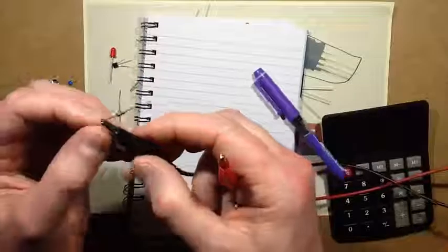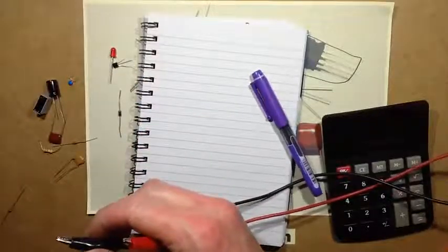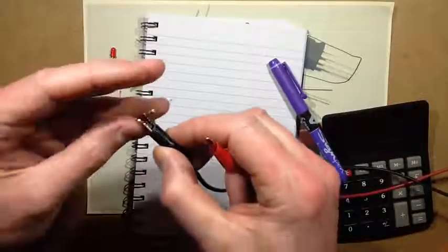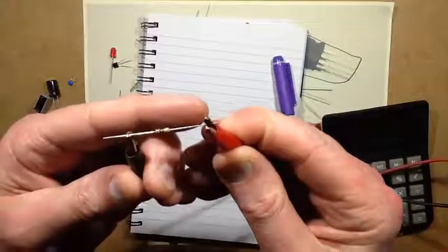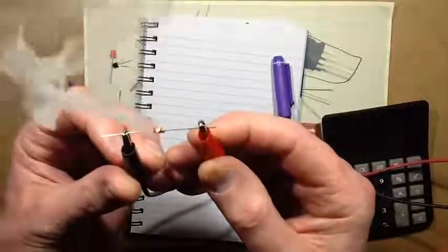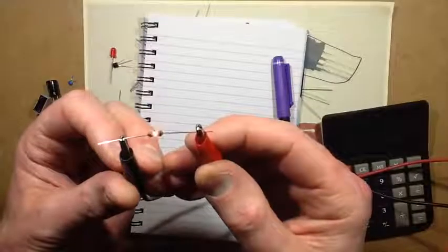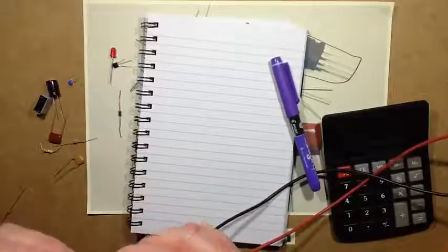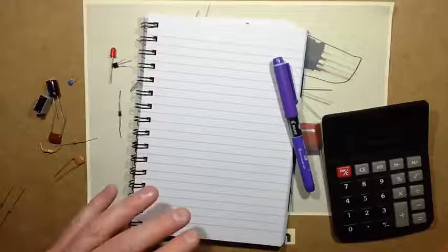Okay, would you like to see that again? Yes, you would. So let's get another 10 ohm resistor here. Hook it up and we'll see it burst into flames again. Oop. Lots of smoke and my workshop is now absolutely stinking. So yeah, you have to choose the correct power rating for resistors. How do you work that out? That's where another formula comes in.